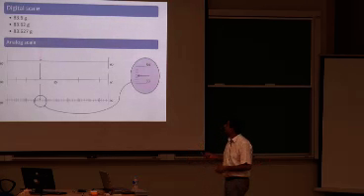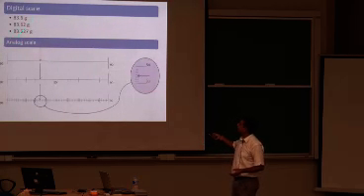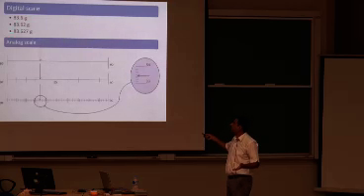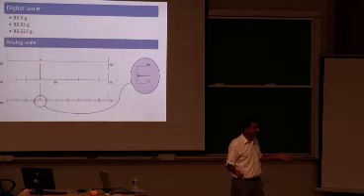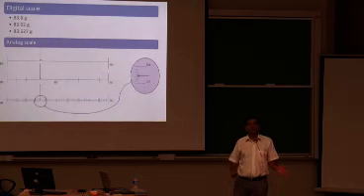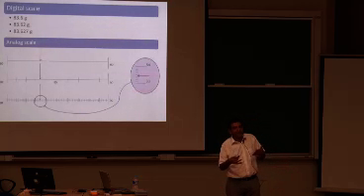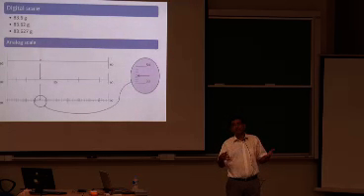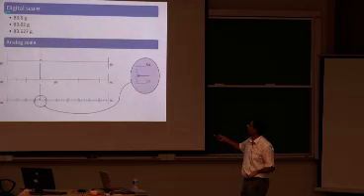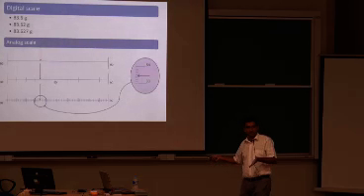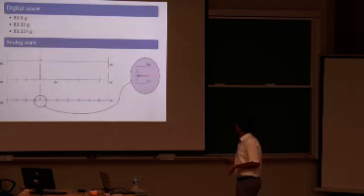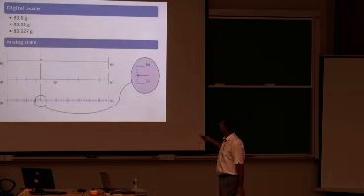On a digital scale you get readings of this kind, 83.6, 0.62, 0.627, depending upon the sensitivity of the balance. What does sensitivity mean? What's the least measurement that it can make? Here it can measure hundreds of milligrams, here it can measure tens of milligrams, here it can measure milligrams. Now, consider an analog scale.